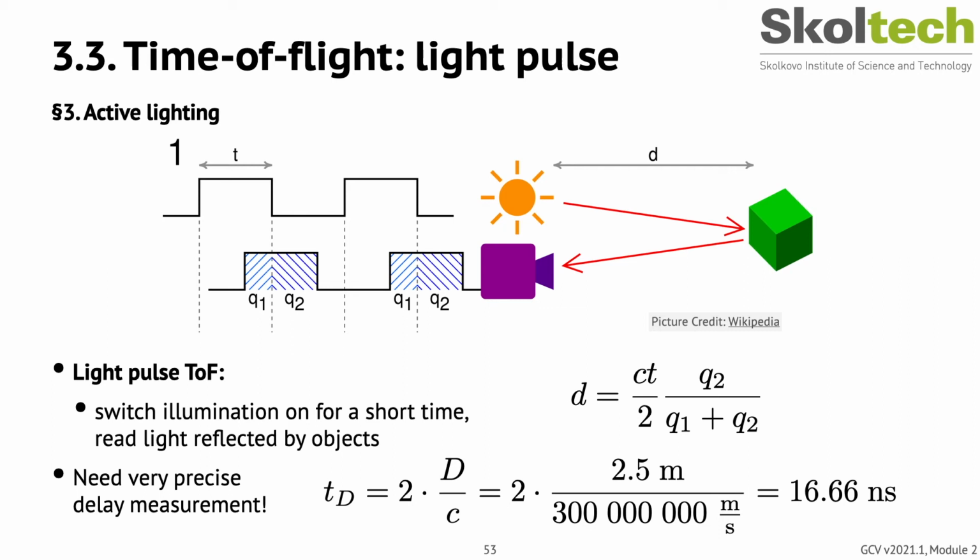The simplest version of a time-of-flight camera uses a series of light pulses or a single light pulse. In this case, the scanner emits a focused pulse of light and waits for it to return to a sensor. The time it takes for the light to return, multiplied by the speed of light in air, tells us how far the pulse traveled.